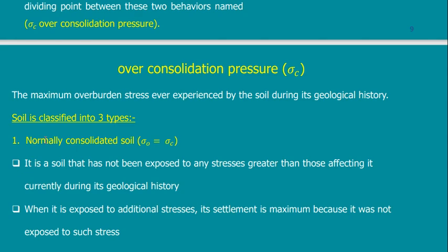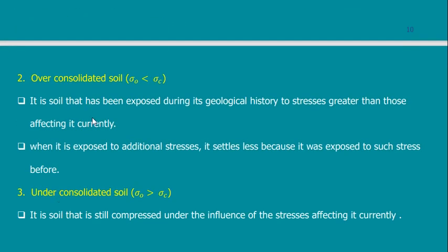In this case, it will be called over-consolidated. Why over-consolidated? Because I'm stressing it with a stress that it faced a long time ago, but I'm doing it again. I usually compare it to human beings. If you are grown up, you are very well experienced, you are subjected to many problems and stresses in your life. So when you face a new problem, it is similar to a problem that you have faced before. But if you are just freshly graduated or just a teenager, then you will find that you are facing problems for the first time in your life.